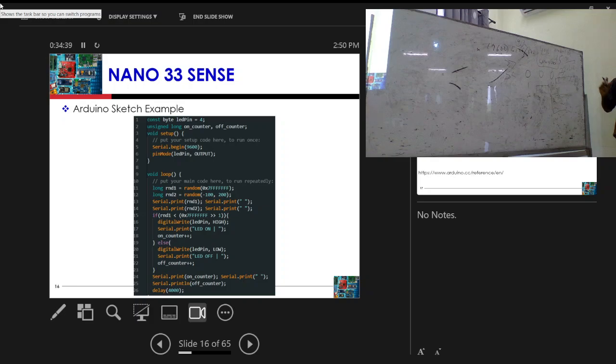This is very important. If you write inside your code and use the divide operator, the division operation is very, very complex. Division uses a lot of hardware. Division uses a lot of power to run before it gives you an output. So somebody can think, if I'm dividing a number by 2, can I use an operator that will use less hardware and less power? And you will then begin to think.